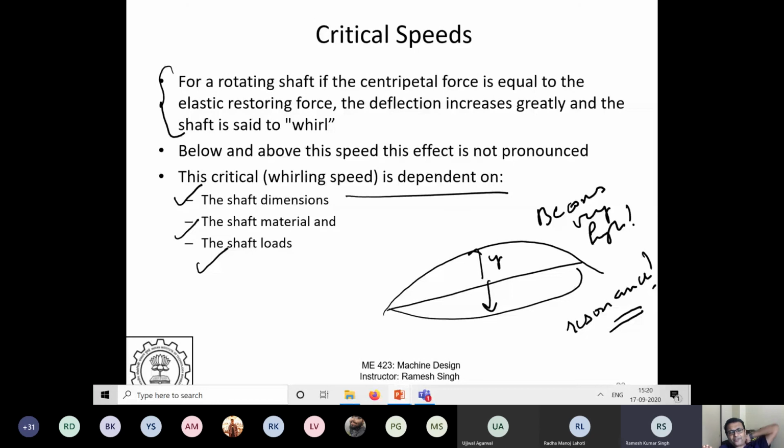So typically, if somebody is using a gas turbine, the operational gap between the natural frequencies should be enough, so that you do not hit the natural frequencies while operating. What they do typically in gas turbines is they operate between 1 and 2 or 2 and 3. So there is a wide gap between the two.